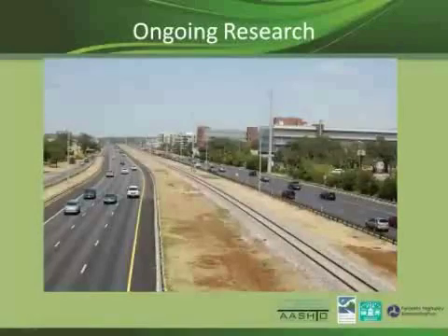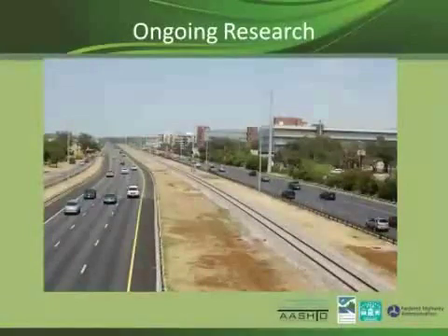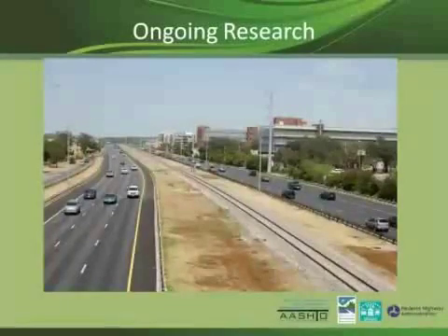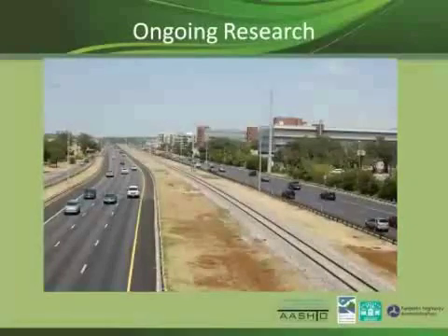And the other thing we're seeing is on the right side, this pavement incorporates recycled rubber in the asphalt binder, whereas the pavement on the left does not. And as Eric mentioned about zinc and tires, we always see substantially higher concentrations from the side with recycled rubber in it. What we're doing now, and I think we'll start in the summer, is look at some amendments to the pavement, like adding sorbents in the pore space so we can get improved removal of dissolved constituents, primarily metals and possibly dissolved phosphorus.